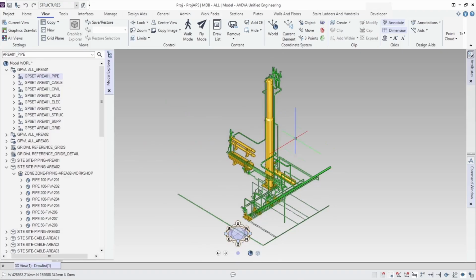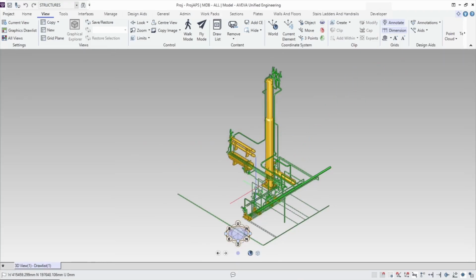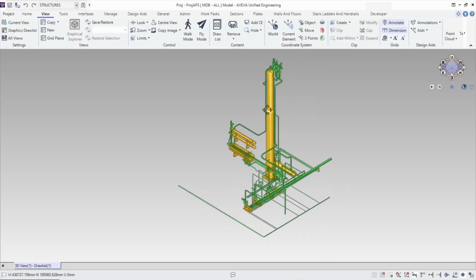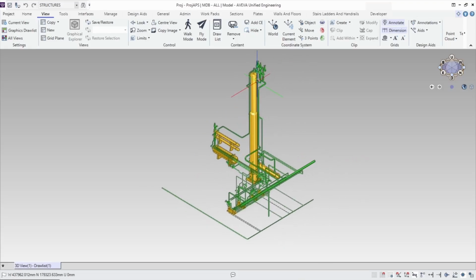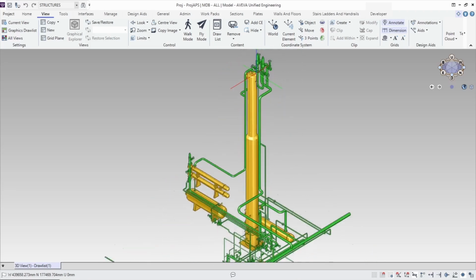Remember that to maximize the modeling area, the Clear Canvas button in the corner of the screen can be used, giving us more space to work on the model. Once elements are in the view, navigation is handled using the mouse. Pan by holding the middle mouse button along with the control key and then move the mouse. Zoom by scrolling the mouse wheel forwards or backwards.